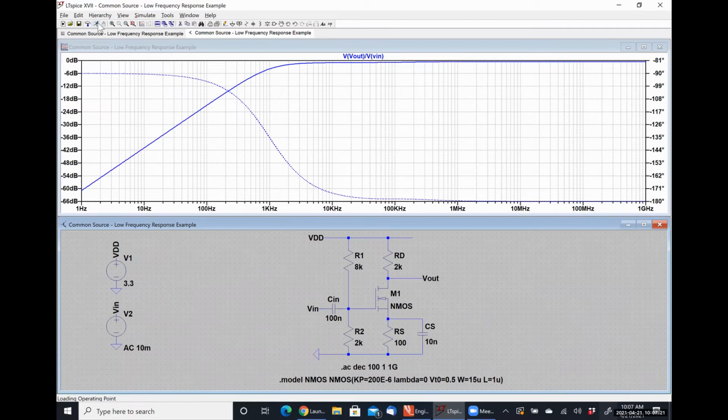And we can much more easily see that pole at 1K, but we're effectively losing our higher frequency pole. It's because that zero occurs so close in frequency that it's a dip and it immediately flattens out. So we have what we would expect, a high pass filter, when we're looking at this for low frequencies, right?